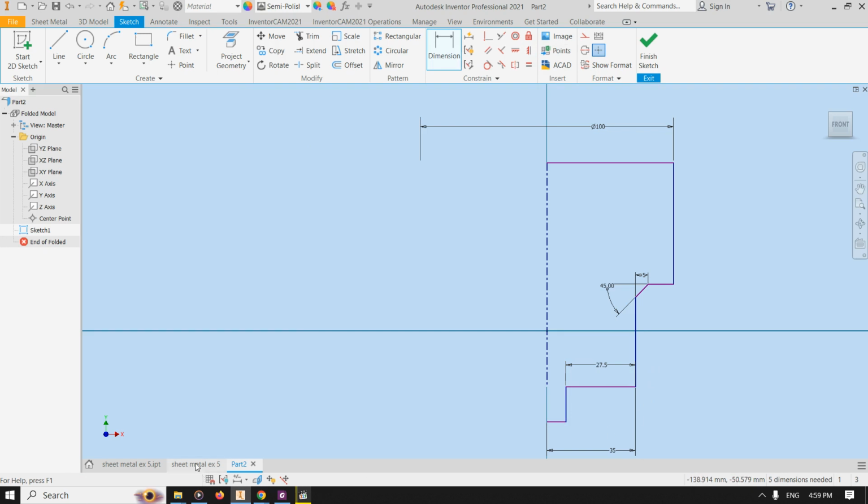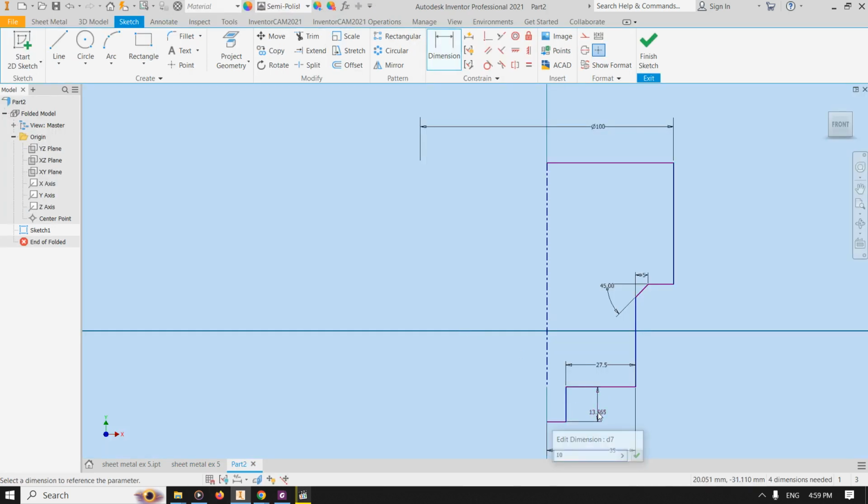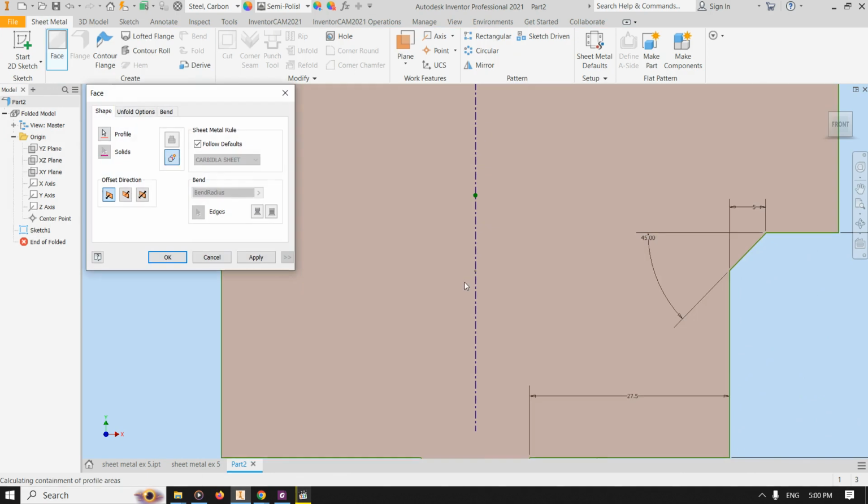That's correct now. And for the height, I would use these parameters 90, 30, and 50. So this section is 10. I will give 10 and 30, 50, and the hole would be 90. That's okay. Then we use the mirror tool, select entities to be mirrored, and then select the mirror line, and then apply. Done. Then we go finish, and then sheet metal, and then select face.